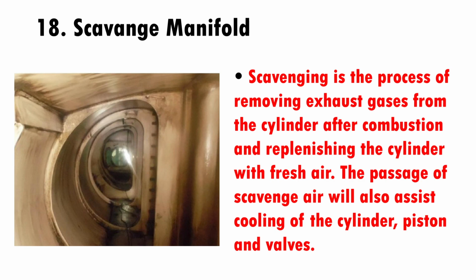Scavenge manifold. Scavenging is the process of removing exhaust gases from the cylinder after combustion and replenishing the cylinder with fresh air. The passage of scavenge air will also assist cooling of the cylinder, piston, and valves.